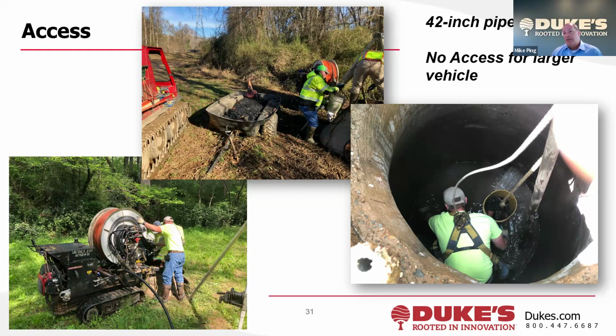So if you're looking at this, it's off-road, right? There's an easement machine. If you go over to the right picture, they can't get the vac truck there, so this guy has to get in the manhole and physically shovel it out. He's hooked up. It's a confined space, with a lot of safety gear, a tripod, all that sort of thing. You can see it in the top picture even. He's shoveling, bucketing it out, one 5-gallon bucket at a time. You can see these are all 3 pictures of the same application.